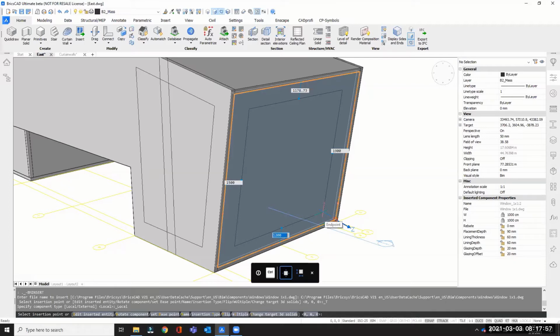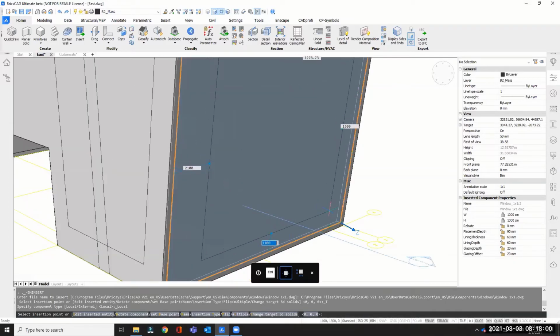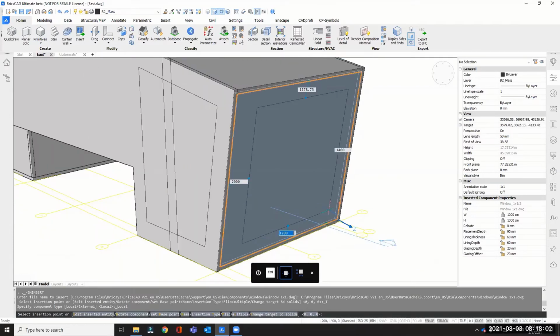So you see that we have our dynamic dimensions being highlighted in blue. So to be able to input the information, I might just want to type in the numbers. So for example, on the left side, I will click on tab. So remember that you just click on tab so you can go into each of these dimensions. And on this left side, we might want to put in 1007. So just click tab, and then it will instantly be locked and placed into the 1007 millimeters away from the leftmost side of our wall.